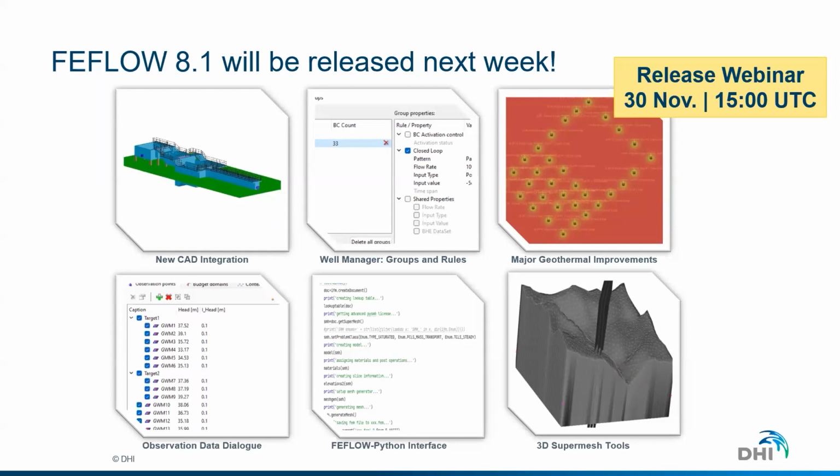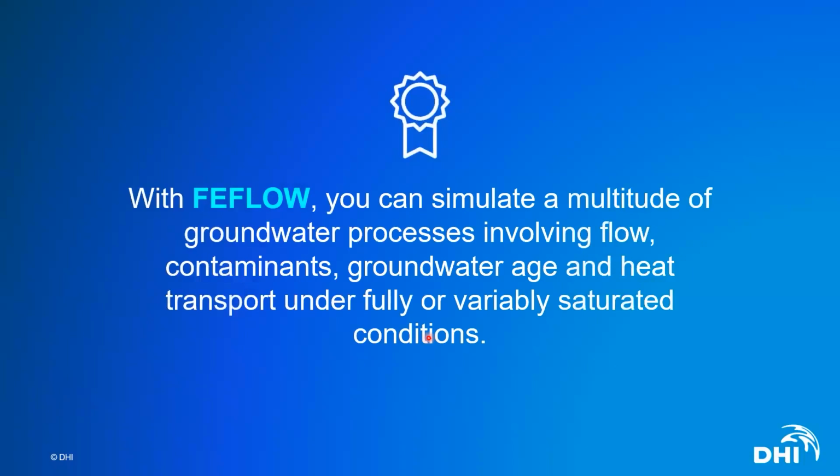For those new, FEFLOW is a finite element software that has already been around for many years, since the late 70s. We have been developing FEFLOW since that time. FEFLOW is capable of simulating flow, contaminant transport, groundwater age, and heat transfer under fully and variably saturated conditions.